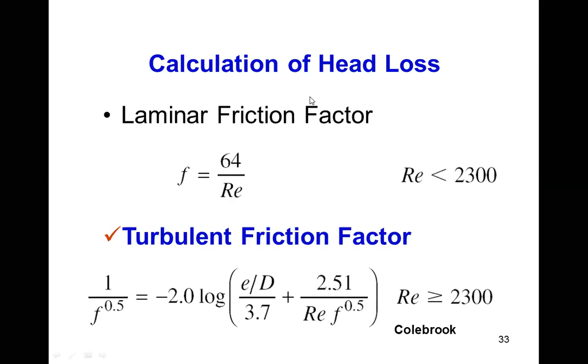So the friction factor for laminar flow, we have 64 upon Re. This we derived in the last class from the Poiseuille equation. Is this fine or not? This we derived in the last class. We got 64 upon Re for laminar flow in a pipe. Yes, sir. Right.